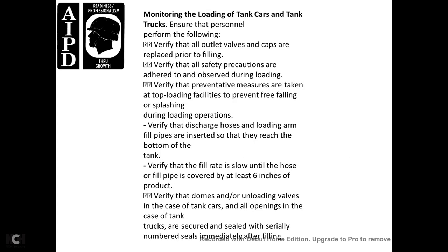Monitoring loading in tanker cars and tanker trucks. Ensure that the personnel perform the following: verify the outlet valves and caps are replaced before filling. Verify all safety precautions are adhered to and observed during loading. Verify preventive measures are taken with the top loading facility to prevent free falling or splashing during loading operations. Verify the discharge loading arm fill pipe is inserted so that it reaches the bottom of the tank.